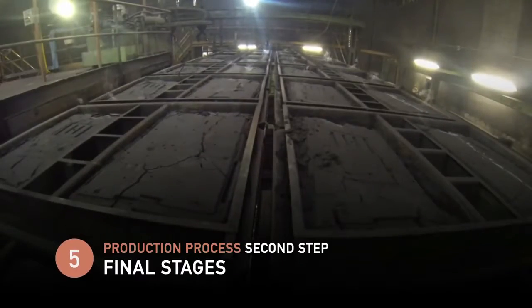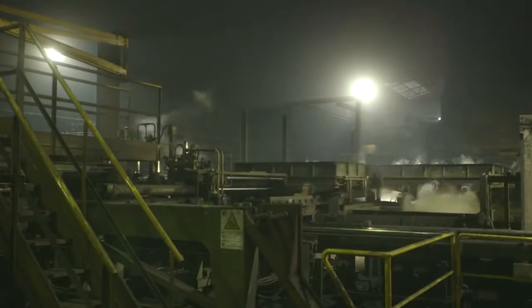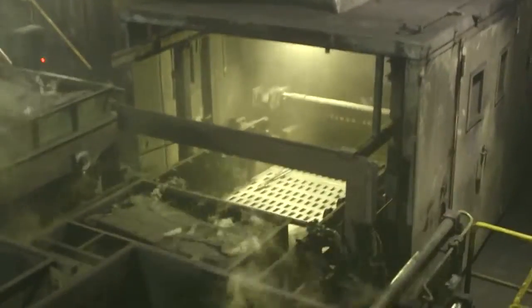After casting, the cast iron products are left to cool on the floor for 50 minutes, then taken out of the flasks and placed on vibrating platforms to clean off the sand produced by the core breaking up inside.